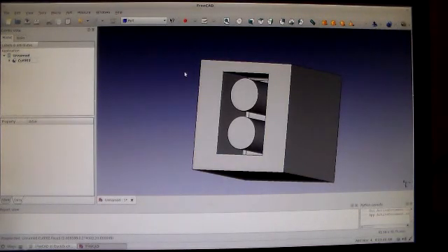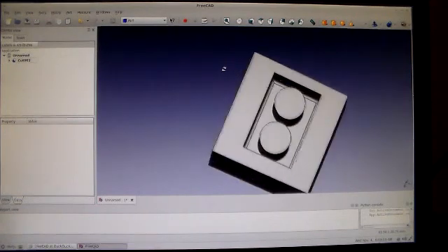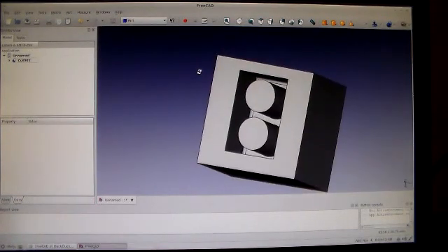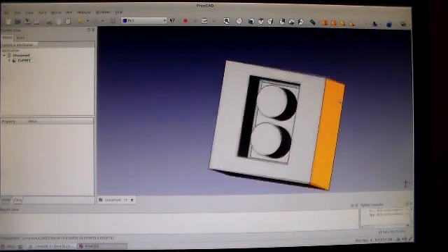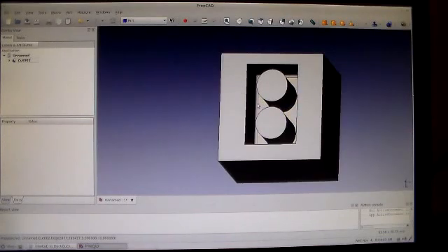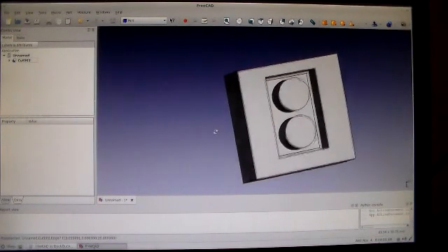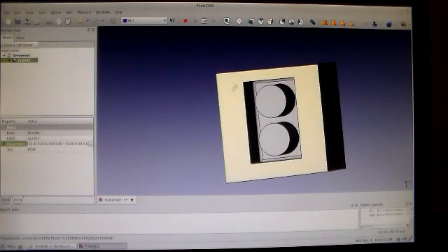Now you can see I have a shape that, using other drawing methods, might not be terribly intuitive to draw, but it has a radius down on the bottom because we put the radius on our part, so it cut it out exactly to that shape. And again, we could hold the Control key and now put some radiuses on our box here,